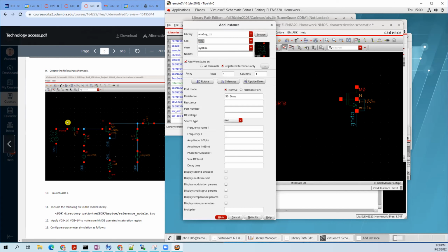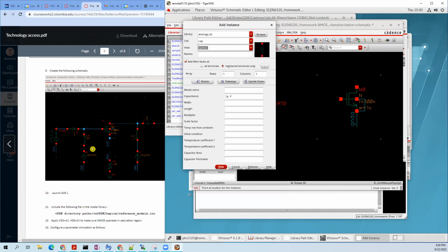And in here we can see we use a very large capacitor and inductor. The reason we use a very large capacitor, which is like 1 farad here, and the inductor is like 1 Henry, is that at high frequency, the capacitor acts like a short circuit and the inductor acts like an open circuit. So the DC doesn't affect the signal at high frequency.